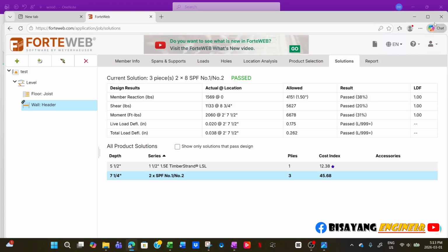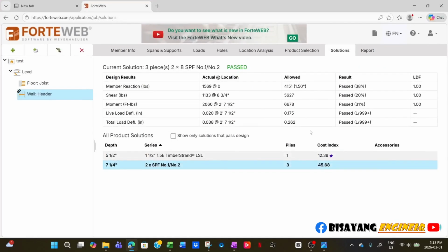That's basically the main reason, because if you are working on, for example, a residential or shop building, you will really experience that there will be a tenant improvement or renovations in the building. So there will be changes in the loading. So that's why it is better to just over design that one.